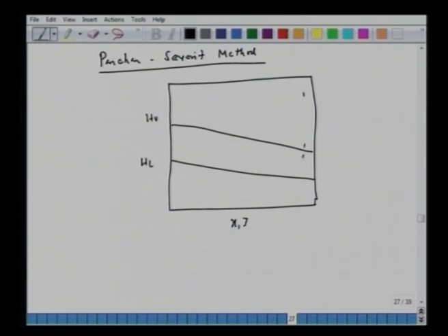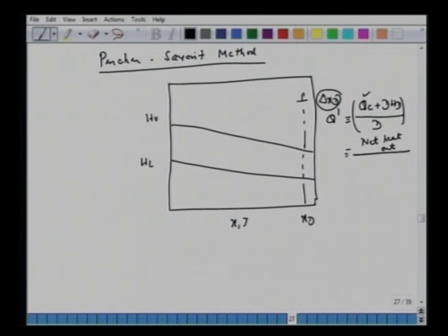Then we said that corresponding to this xt, say in case of total reflux, we mark this point del xt, which corresponds to the coordinate q dash, which is qc, the condenser load, plus d hd, divided by d. So a hypothetical stream leaving the system with the condenser load and the top product. So that was our q dash, which is nothing but net heat or energy out over net molar flow rates.